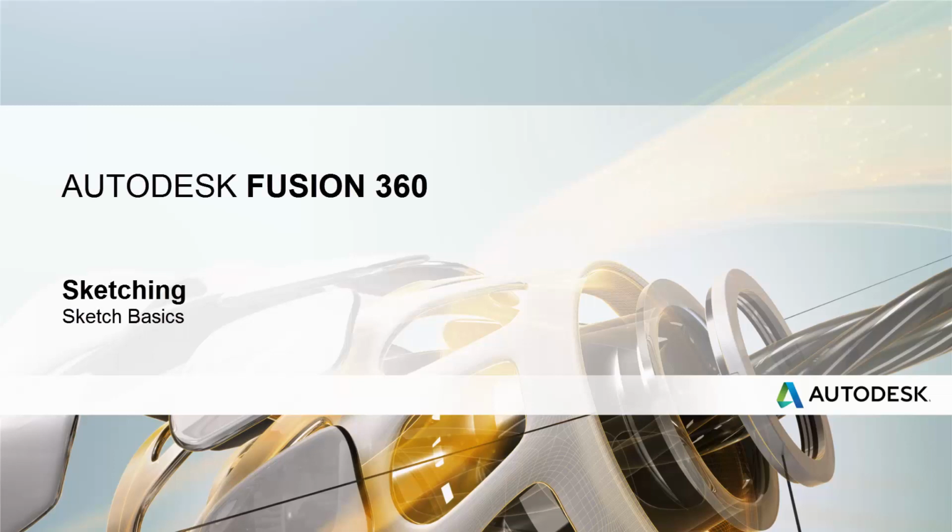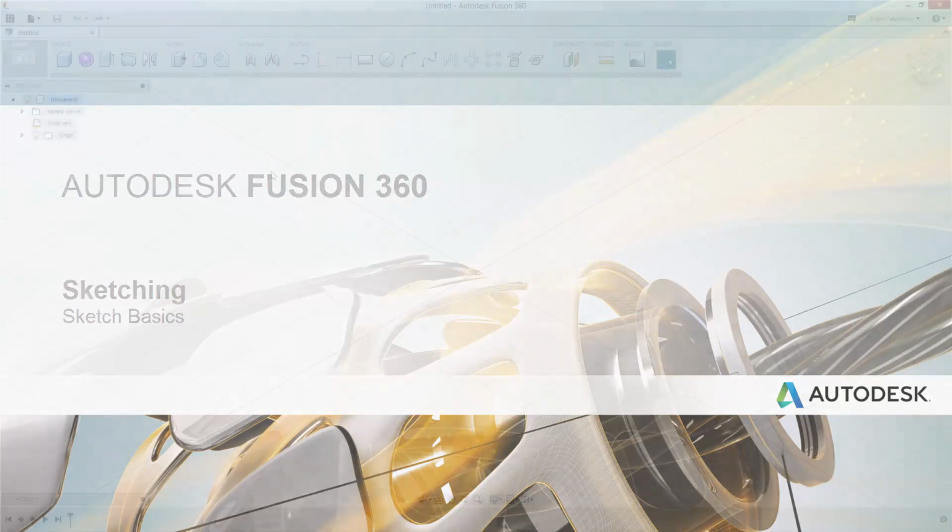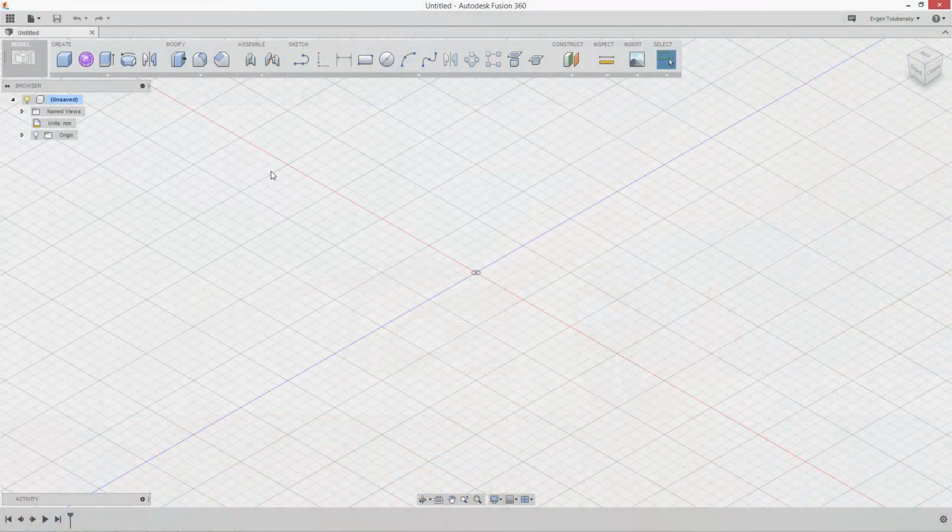Many features that you create in Fusion 360 start with a 2D sketch. In order to create intelligent and predictable designs, a good understanding of how to create sketches and how to apply dimensions and geometric constraints is required. Fusion does support 3D sketches, although in this module, we will cover basic sketching tools to create and edit a 2D sketch. In this exercise, you create a new Fusion design, then create a new sketch in the design.